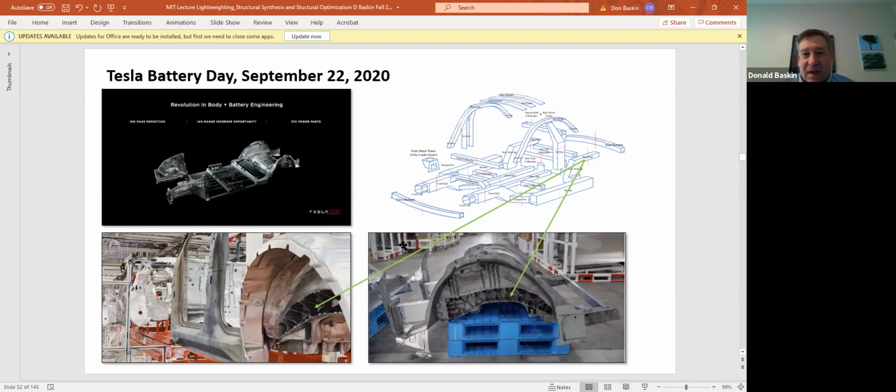I think the Chrysler, if I remember correctly, has around 300 different stampings in the body structure. The Mercedes has about 600 different stampings in the body structure. Each of those parts, you have to keep track of tooling, and you have to do dimensional checks on each part, and you have to have a separate quality control person for each part. So it's a tremendous effort to keep track of every part. Not to mention you have weight that's tied up in the seams where you join these parts together.